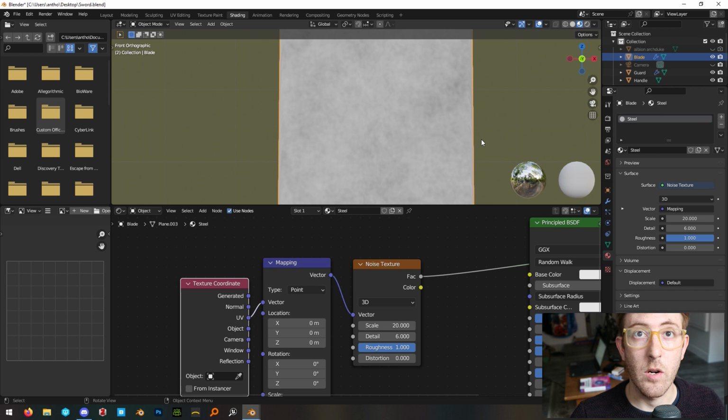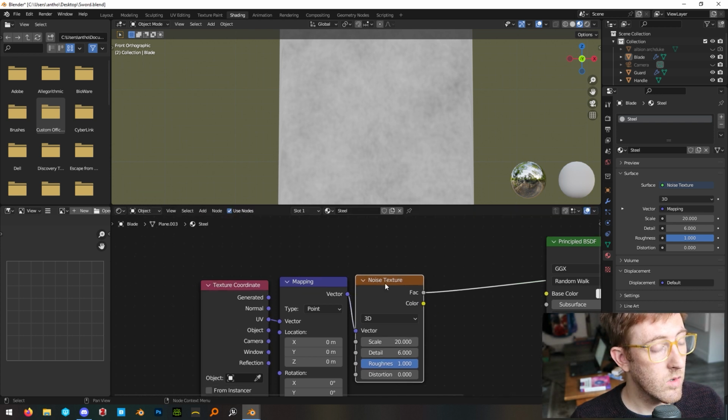And for metal, you generally want the roughness to be low so that it's reflective. In order to do that, we need to bring down the range of these values, so that instead of going from white to dark gray, it goes from a gray to a darker gray, so that we have a range of values, but our minimum and maximum are all still relatively low roughness. I hope that makes sense, and you can do that with a color ramp.